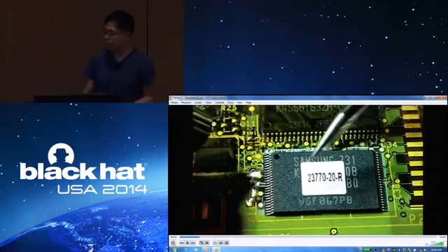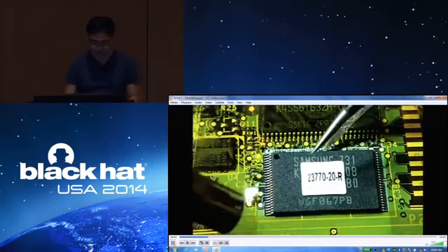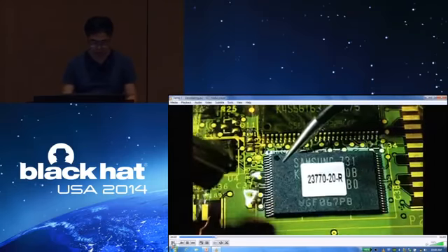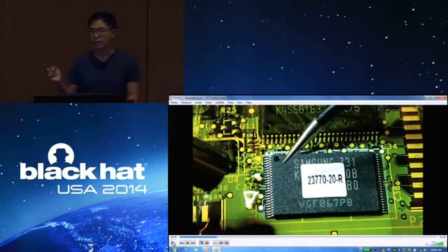So you can see this. Just before this, you saw that the temperature was 330 Celsius, around that temperature. That is the temperature you are using for soldering with the iron, when you are using soldering irons for soldering. So I was just using the same temperature for desoldering. At that temperature, the solder is supposed to melt away.